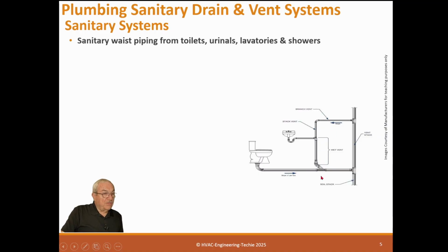The way these happen, and the distances, and how many fittings should be in, is all code driven. And that's fully explained in the design section. So this is the drainage, and this is the vent pipes. The vents are actually way oversized. I mean, to vent a pipe of air, you don't need this large of piping, but it's been field tested. They've got facilities that are solely designed just to test systems. And this has been tested to be totally reliable, and that's why they're the size they are.